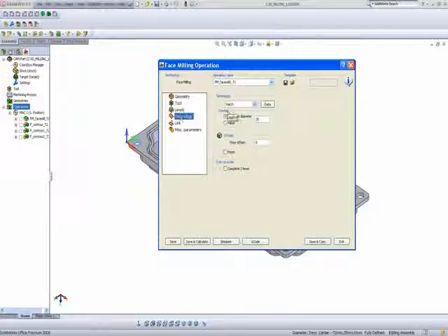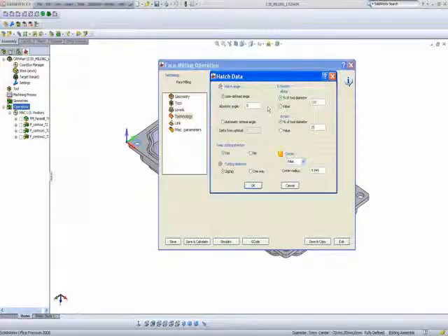My technology, again, I'll be using the hatch, but this time, just to show you the difference in what control we have, I'll use my absolute angle as 90 degrees, so that the tool will actually go 90 degrees across the part instead of 0 degrees.